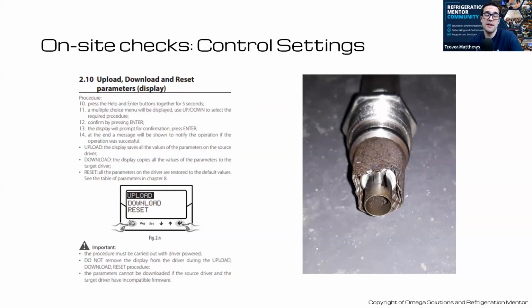Totally. And so this is important to understand. If this starts to plug up, it's going to mess up your whole system. You need your high pressure valve, your flash gas bypass valve, and all your EEVs to work in sync. When you have those working in sync, you're going to have a system running really good, with stable suction, stable liquid, and a stable discharge. And this comes back to fine tuning, which is a whole other conversation with electronic valves and controls.